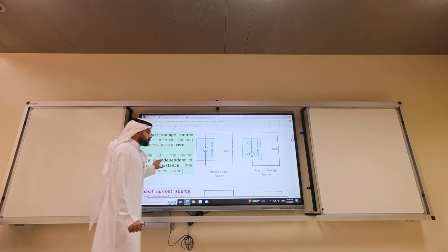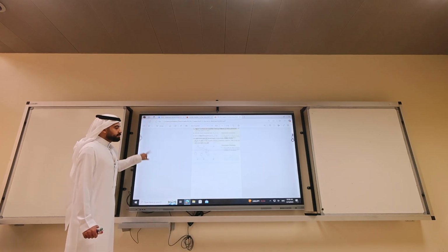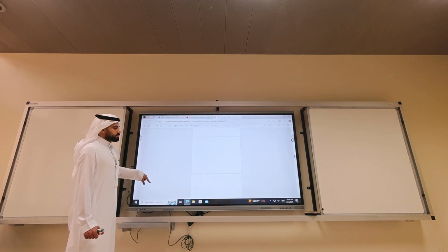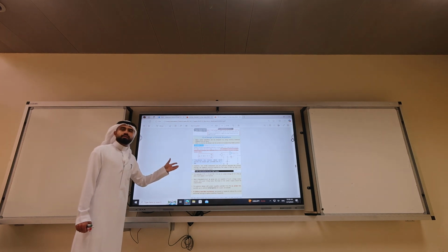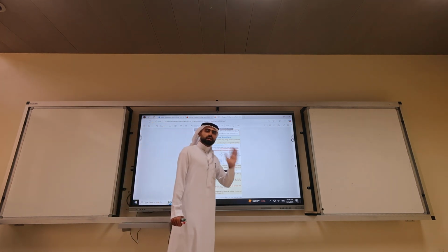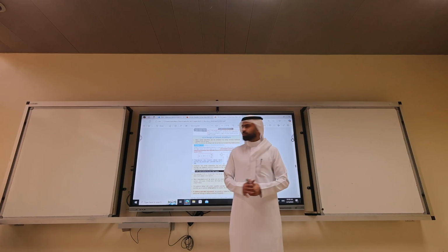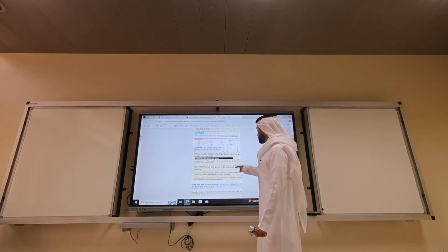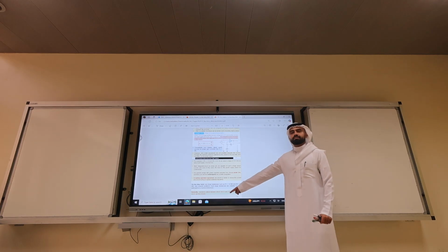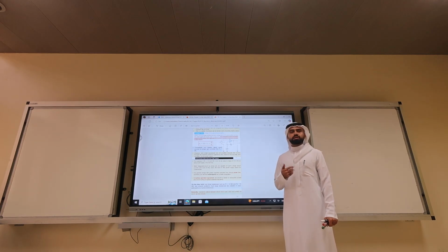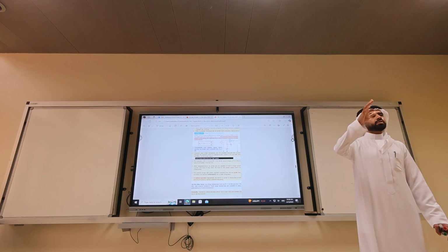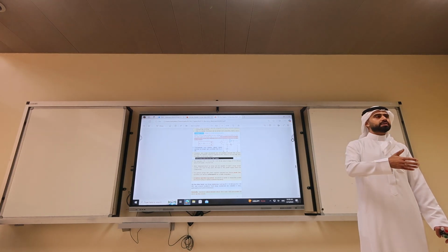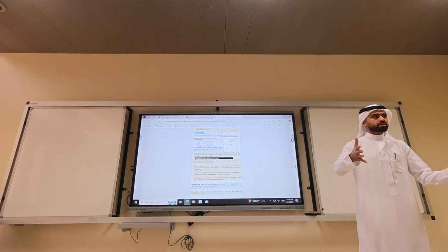Okay? Now, last time we talked about the design of a simple amplifier. And what did we say the range? From 100 ohm to 1 mega. What did I tell you? If you get stuck, use kilo ohms, okay? If you use kilo ohms, you will get currents in milliamps. If you use 1 or 10 or 15 ohm, you will get currents of 1 or 2 amps, which is too large for the op amp.